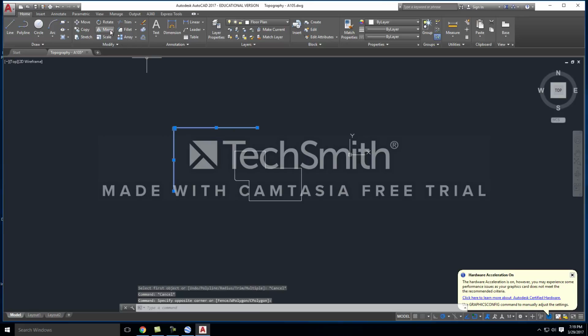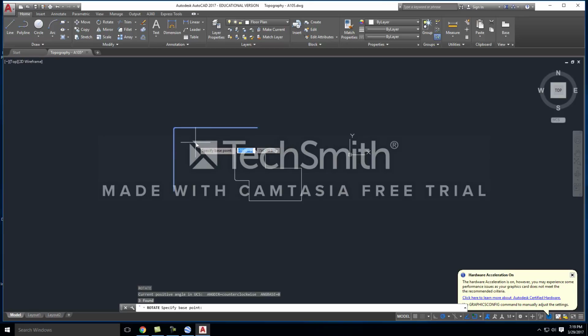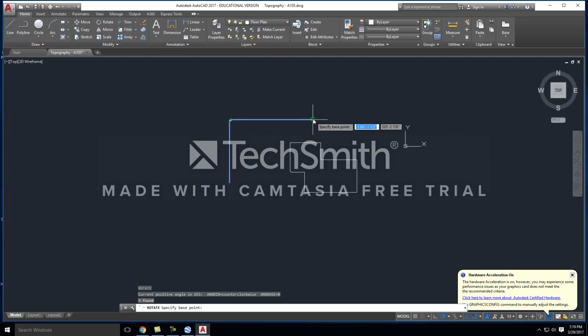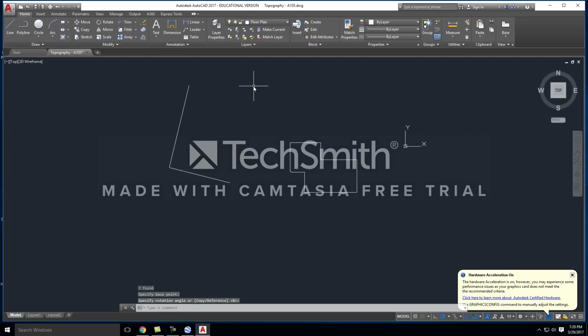Another tool that we did not talk about last time is rotate. If you go up here, you can click on the rotate command. You can also just hit RO. RO is the shortcut for rotate. You'll hit enter, and then it will give you a prompt to specify the base point of your rotation. Think about where you want the center axis of your rotation to be. Do you want it here on the corner? Do you want it over on this side? Notice if I click here, that becomes the center of the rotation of my element.